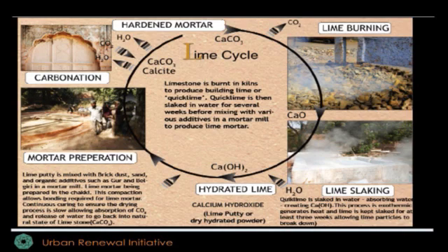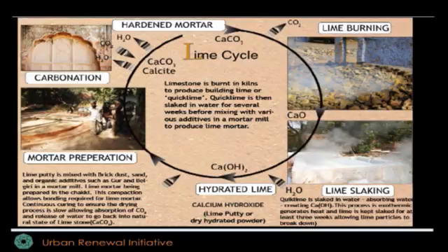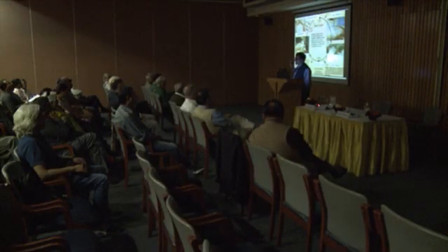You take that calcium oxide and you put it in water, and it's an exothermic reaction, so you can see the heat that is coming out, and the water is absorbed and it becomes calcium hydroxide, Ca(OH)2. What the water does, besides changing the chemical properties, is break down the lime particles into small microns.